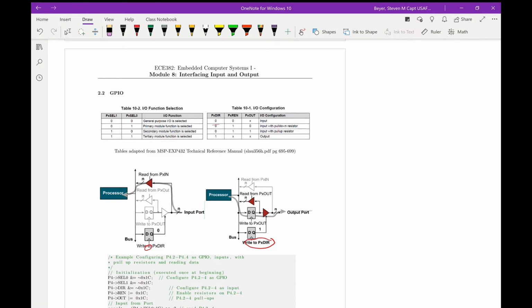And then when we do go to write, we're going to send the next information out to the bit. But we're able to read from the output. And that's not using this because that's a whole separate piece of logic. But this allows us to read from that output, or really what we're seeing is what the previous output was, so that we know what the values are supposed to be, and we can maintain, say, port 4, 0 through 4, we don't care, we're not changing those, but we do want to keep those to be whatever they were before, and then we're going to change maybe port 5.